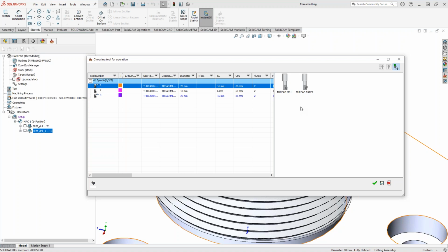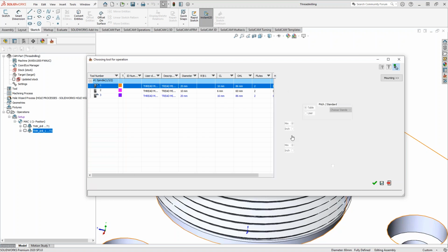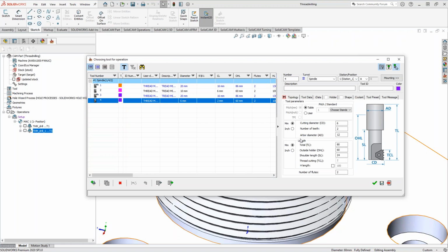So sometimes the tool path doesn't automatically restrict you to a type of tool. Whereas this one is one of those unique ones where you're doing thread milling, you could only choose a thread mill. You have the two types, you have your standard and your taper, but you're really just doing the same thing. You're just defining the tool. So if I just click one of these quick, and Mark, you can see that.